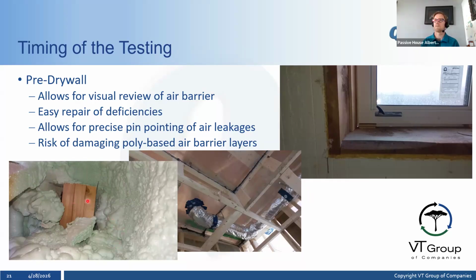There's another detail like this further on in the house where I'm standing on the basement slab and looking up, and I can see the cold air is coming in and around this assembly here, where the spray foam is non-continuous. So that's how I do both. That's how we go about and do this.